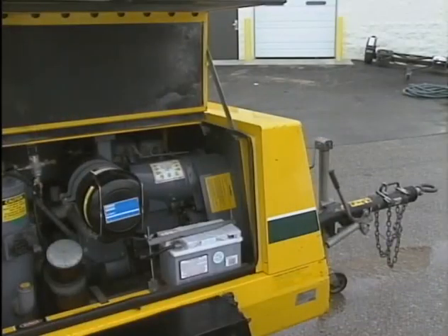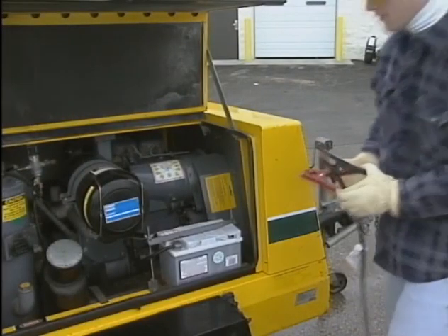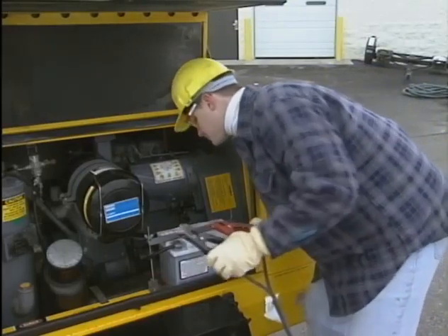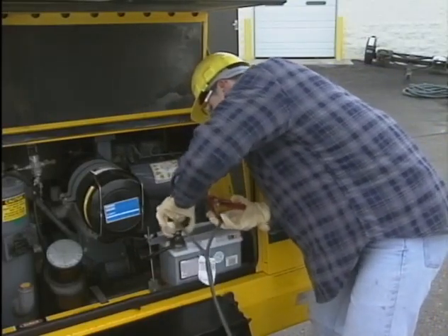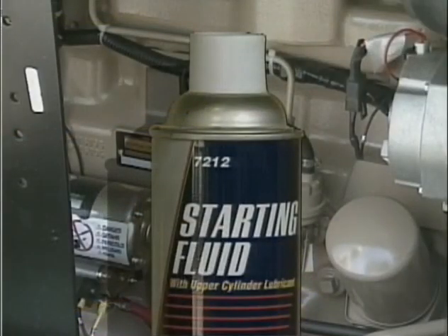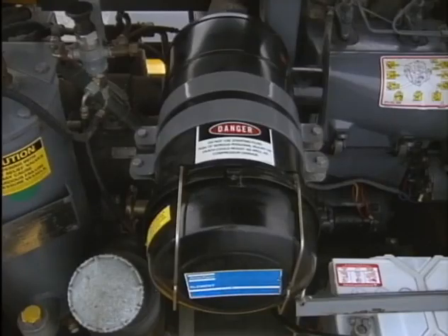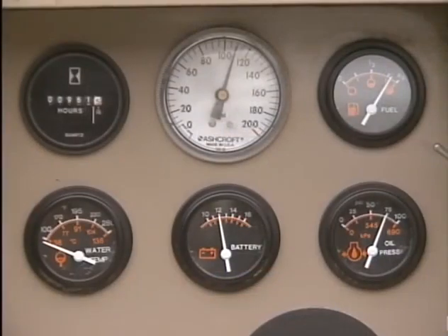Starting aids. If jumper cables are used, follow the manufacturer's instructions. A battery explosion could result from improper procedures. When ether cold start fluid is required, always read the instructions before using. Ether is highly flammable. Do not inject ether into a hot engine or an engine equipped with a glow plug type preheater. Do not inject ether into the compressor air filter or a common air filter for the engine and compressor. After starting the engine, observe gauges, instruments, and warning lights to assure that they are functioning and their readings are within the normal operating range.